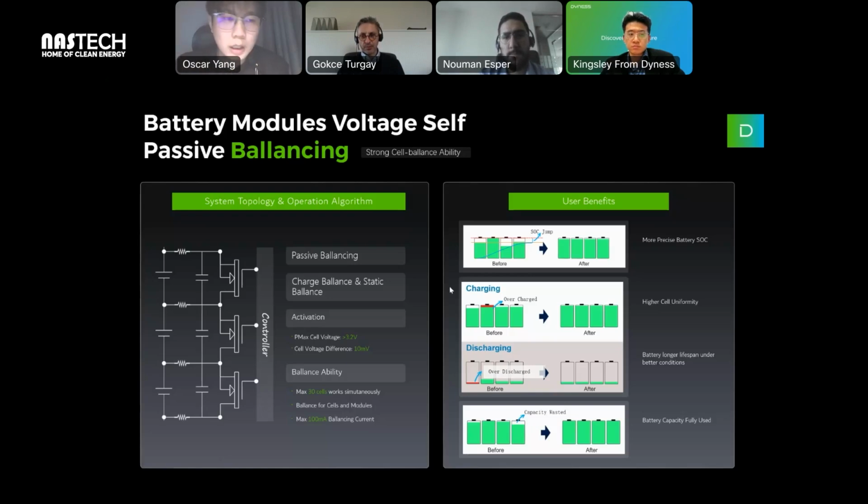For the LV residential battery, we are not using any air cooling or liquid cooling. We just control the battery temperature through the BMS board, because the hottest situation is when you are charging it. So we limit the C rate to 0.5C or maybe 1C. This kind of C rate makes a good balance between performance and temperature.